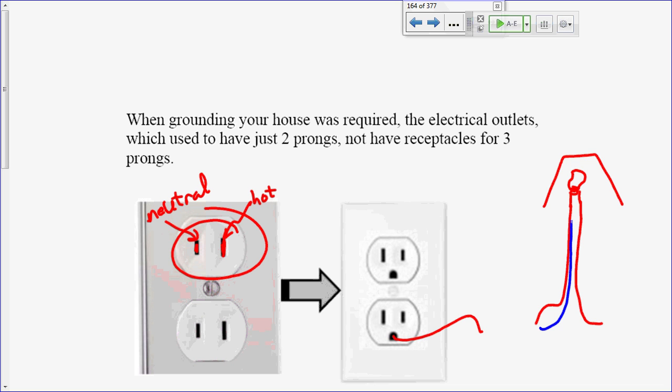Right, you have a wire that comes in up here, and then you have a wire that comes in up here. They try to design the lamp so that the hot wire is as short as possible, so that there is as little possibility for you to have a short within the device as possible. So they try to make the hot wire really short.